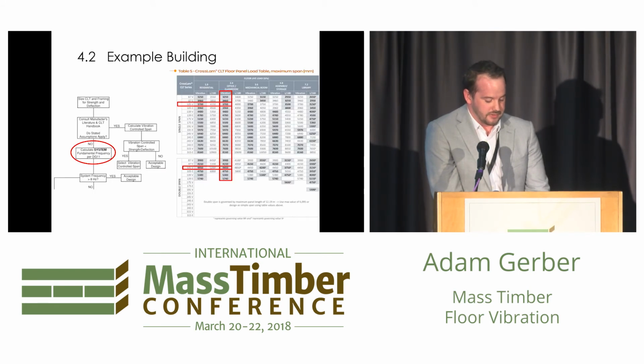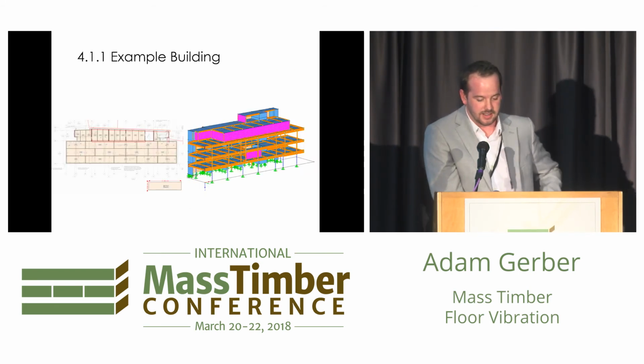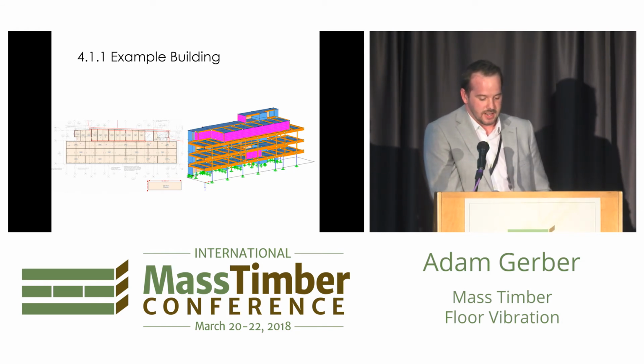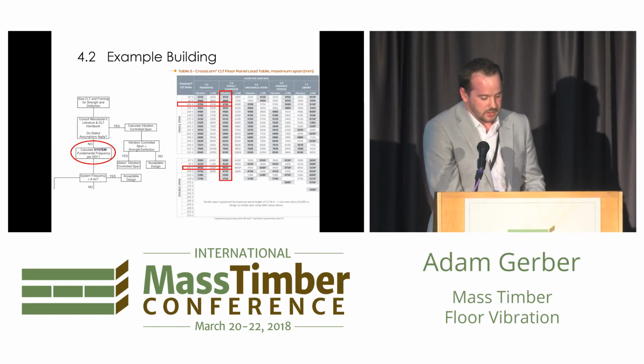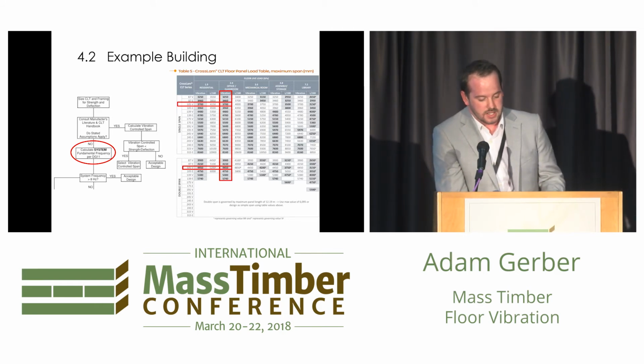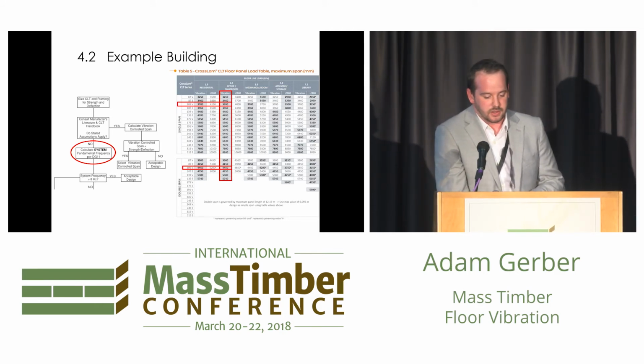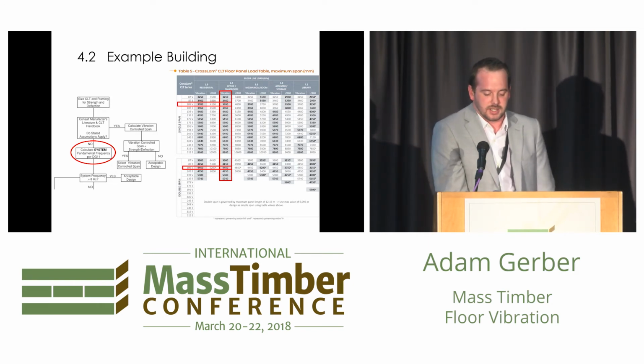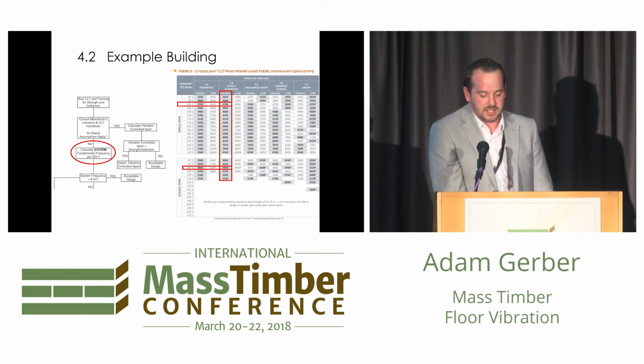So quickly, I have an example from a structure that we were involved in on the specialty engineering side, and just as part of our diligence on the project, we went through and did a quick check of the vibration performance of the floor. And so illustrating the use of the flow chart, does it meet the requirement of a well-supported floor? It was CLT beams spanning 12 feet between, CLT panels spanning between beams spaced at 12 feet on center. And so automatically we're sort of kicked into the not well-supported floor system.